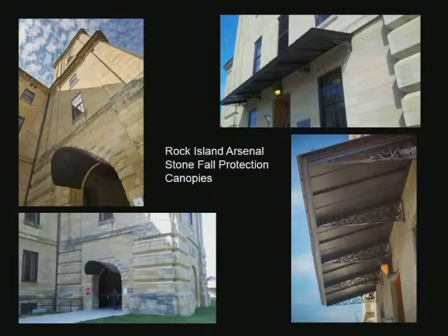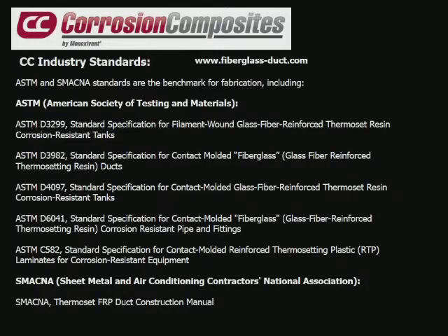That interior layer is a corrosion barrier, and we can fill that with the graphite powder. We can use a carbon veil, which is conductive, and that can be grounded, and that is a typical application for grounding duct systems.